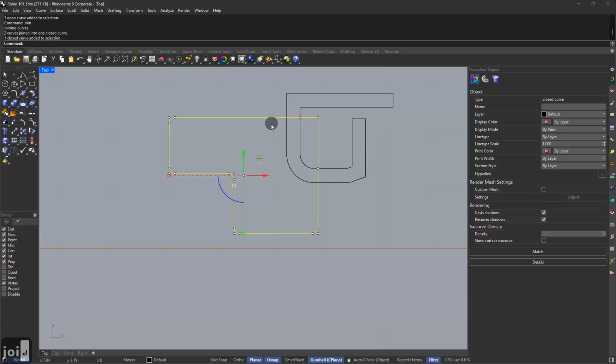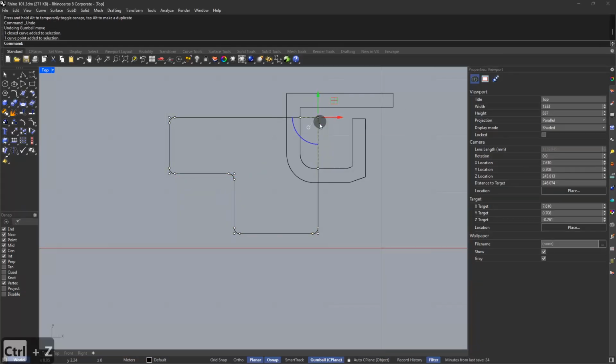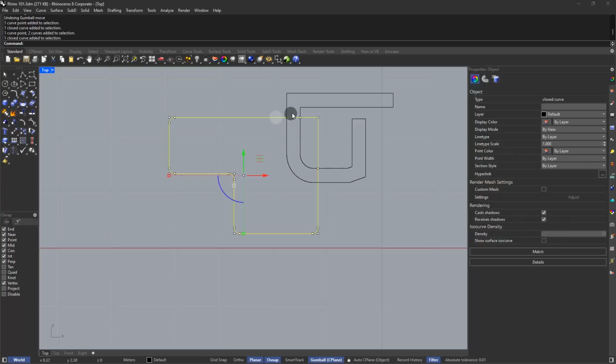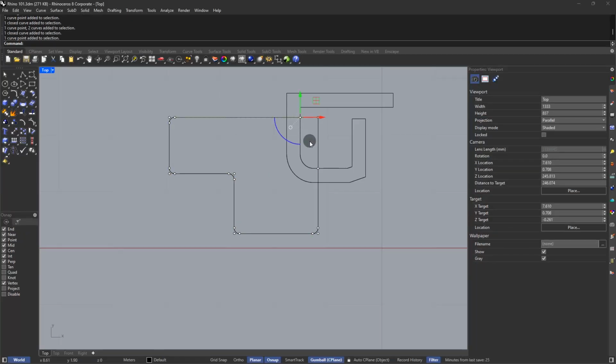If you select your curve, as you see, we have these control points, but for example, for a reason you don't want these control points. For example, if you want to change this control point position, it may not be the exact shape you like. So you can just select these control points like this. You can't select it like this because it will select everything, but you just select your curve and you select it this way and you hold shift and you select these two and you will use delete. So for example, you can change your curve like this.